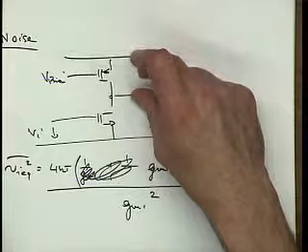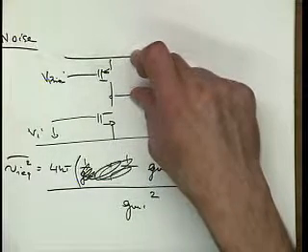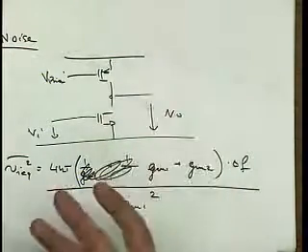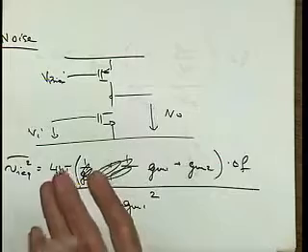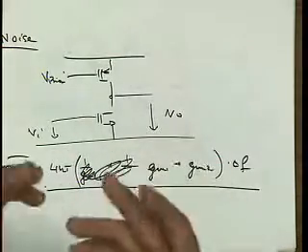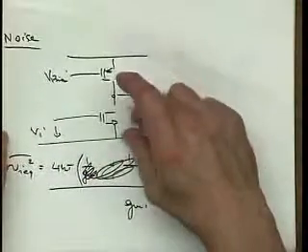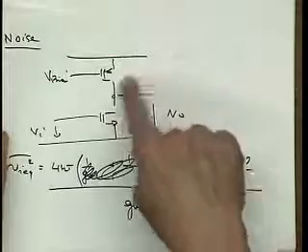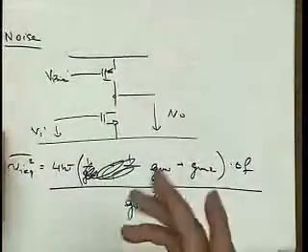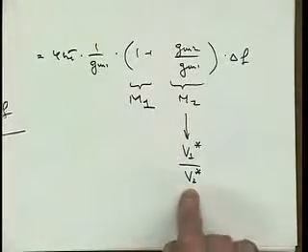Ultimately we are interested more in signal-to-noise ratio than in noise alone. Making V star big reduces the signal, and it also reduces the noise, but there ought to be some kind of compromise. In particular, because the voltage headroom goes down, the signal power is hit with the square, while the noise goes down only with V star.